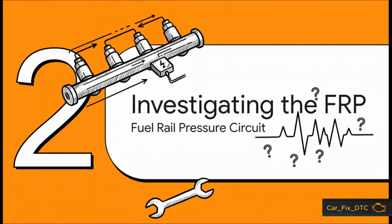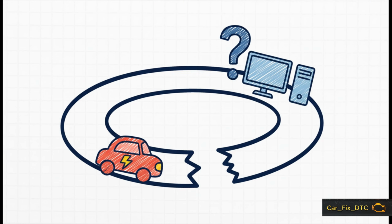Okay, our investigation begins with the fuel rail pressure circuit, or FRP for short. The signal that's causing all the trouble starts here, so it's the most logical place to start looking for clues first. So, our first suspect is what's called an open in the FRP circuit. The easiest way to think about this is to imagine an electrical circuit is like a racetrack. An open is like someone came and took out a whole section of the track. The electricity can't complete the lap, so the signal never makes it back to the computer.